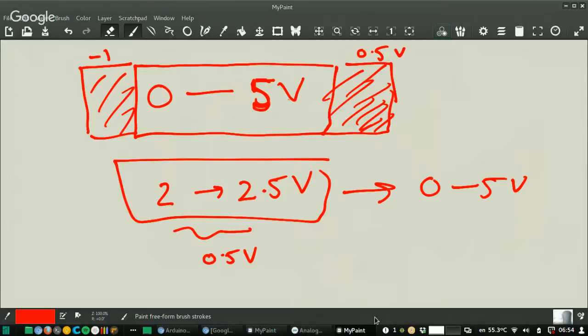Yeah, the thing about what you were saying: for me, I haven't seen any sensor delivering 6 volts or something like this. If this is the case, I think in the datasheet they should say how to do a voltage divider, to get this down.